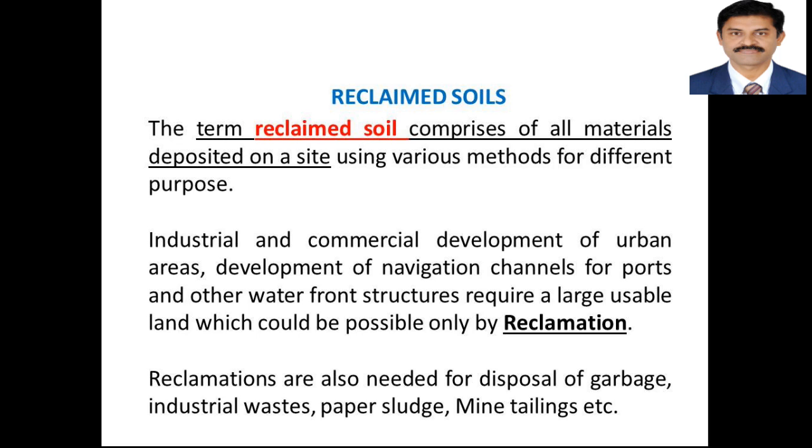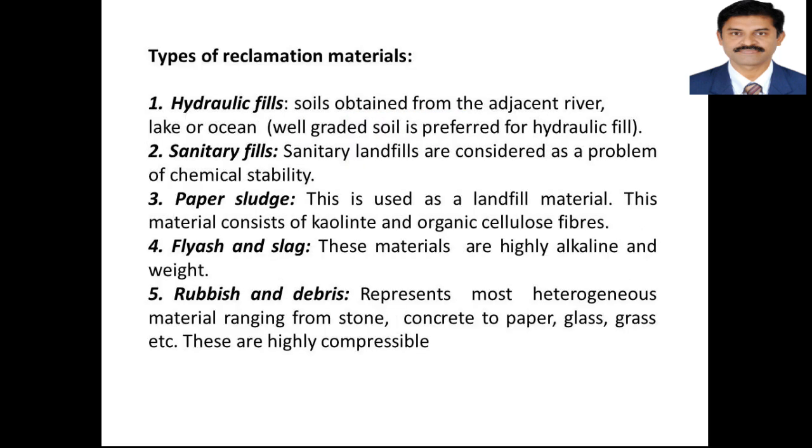Now we will see different reclamation materials. Majorly there are 5 materials. First one is hydraulic fill. The soils obtained from river or lake or ocean are used for hydraulic fills. Well graded soils are preferred for hydraulic fill.